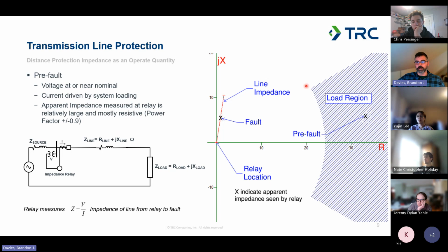And this is, if you plotted it all the way around and didn't have any angle blinders on it, this would continue and it would be a circle around the origin. So this value is your load. And generally your transmission line load capabilities are determined by the conductors or other equipment. There's some limiting piece of equipment on the transmission line itself, but generally we're talking about the conductors themselves, how much power can that conductor transmit.